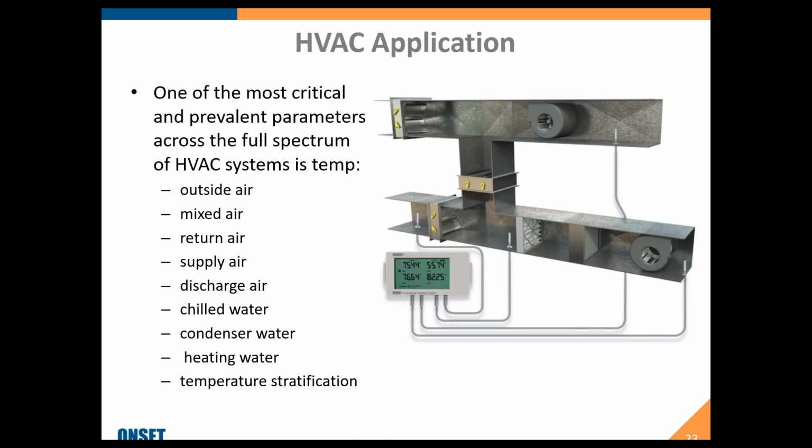So now, one thing is, I've mentioned it a couple times with those 4-channel loggers, but you're able to see it here a little better, is troubleshooting and toolbox items, as we call them. So a lot of HVAC techs or facilities managers or facilities folks will have a toolbox of data loggers. So they'll have one of these UX120s or the MX1105 with the temperature probes and maybe some current transducers.